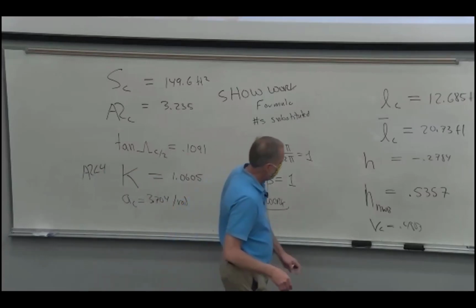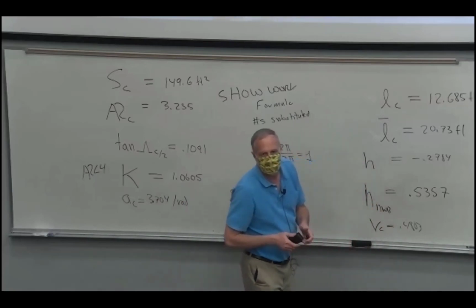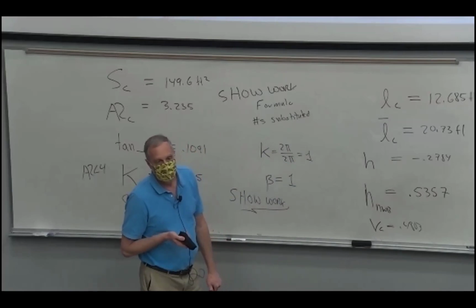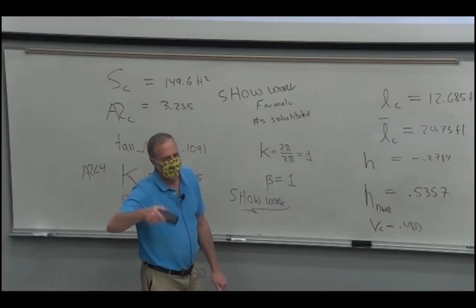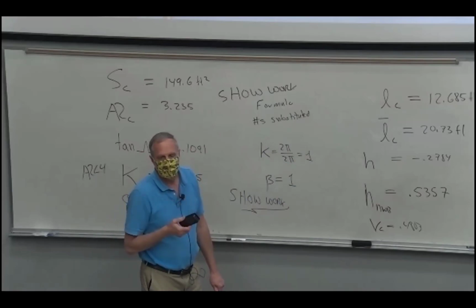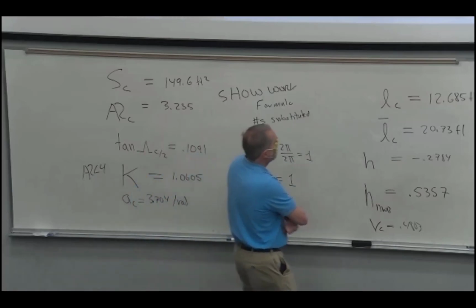So we've spent time talking about pitch trim and pitch stability, so we know how to design an airplane to do that. Most airplanes have elevators on them. So I want to walk our way up to that point by looking at the pitching moment equation that we have now and look at, well, what are the things that we could use to control pitch trim and understand why most airplanes have an elevator on them. So I'm going to write that formula up here.